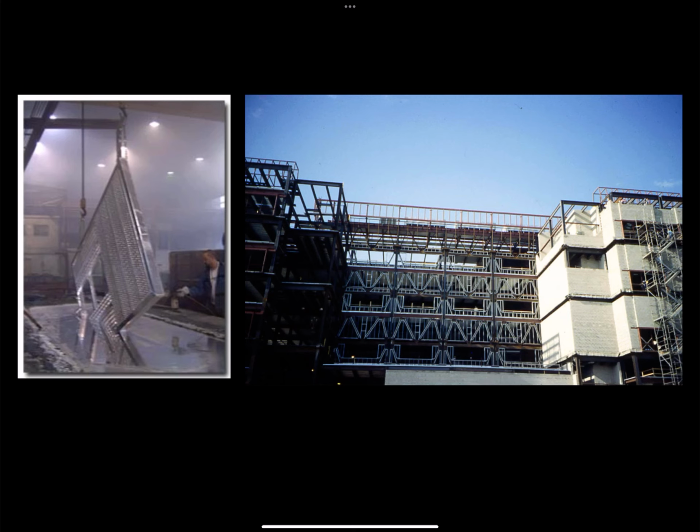And more heavy-duty, larger-scale elements are protected with the dark red or colored paint that you see in the right-hand image, which is protecting them against moisture. So in the image on the right, the dark red elements are the primary steel structure. They're protected with paint. And then the infill elements are light gauge steel studs, and these are all galvanized.